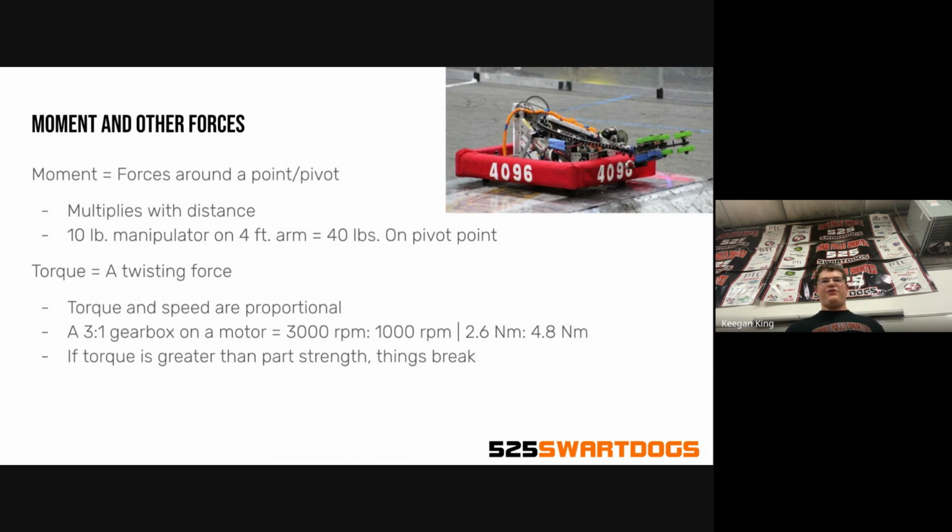And even if the math works correctly with the input and output side, there's the importance of whether the torque you put on the part exceeds what the part breaks at. Like if you try to put a whole bunch of force through a gear ratio or a planetary or something with smaller teeth than it probably should have, you're going to end up breaking the gear before you actuate the arm correctly.